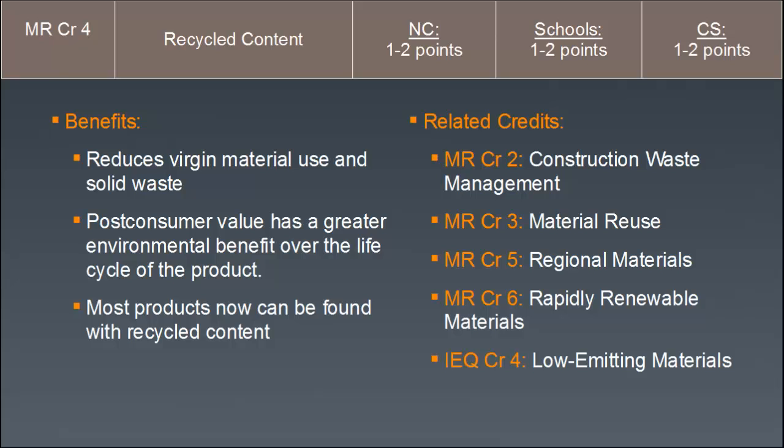And LEED helps you ask those educated questions, like what percent post-consumer recycled content is in this product, or pre-consumer, how much salvage material is in it based on the total material weight. And you really start to get them to think about their claims and ask them what standard they refer to to make those calculations. For recycled content, we saw ISO standard 14021, for example. There are synergies also between the material and resource credits and also with the indoor environmental quality credits for low emitting materials that we'll get to in the next section.